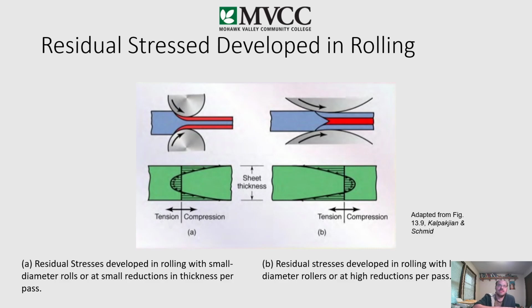What I usually talk about here is if you cut off this top sheet, just half of this thickness, what's going to actually happen is the whole thing's going to want to bend. So we'll end up getting this warping, and it'll actually kind of bend and warp. I've talked to machinists before, and they've seen this. You could physically watch this. Unfortunately, I haven't found a good YouTube video. I'll have to look again this year.